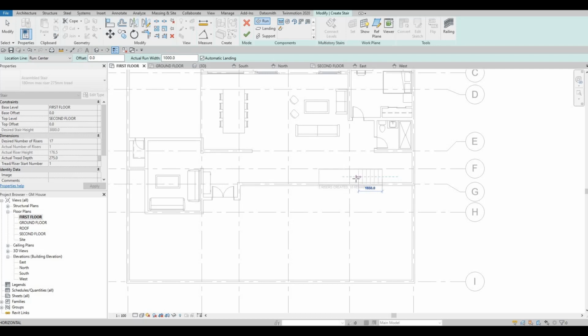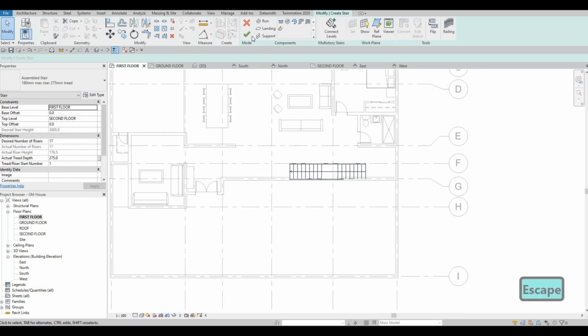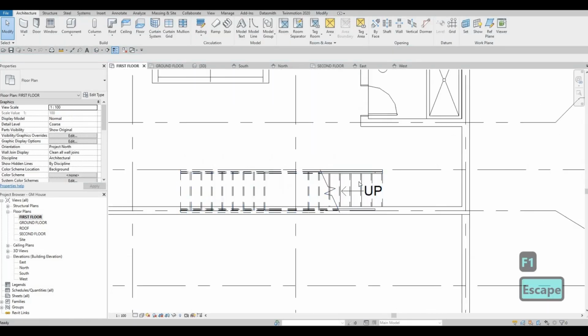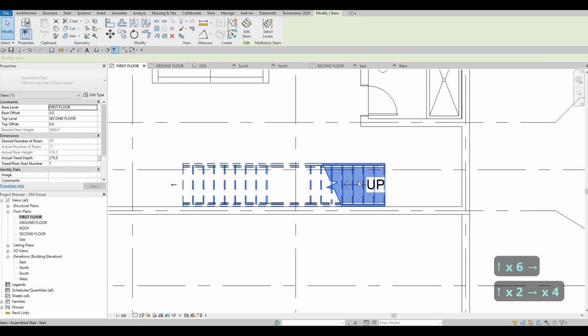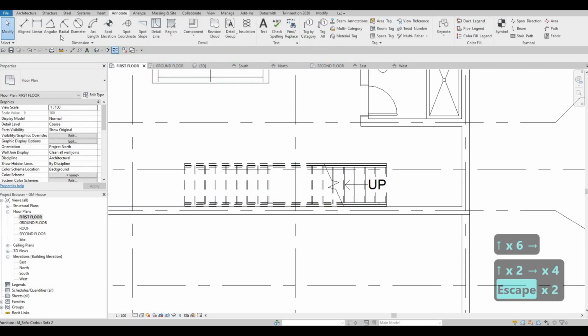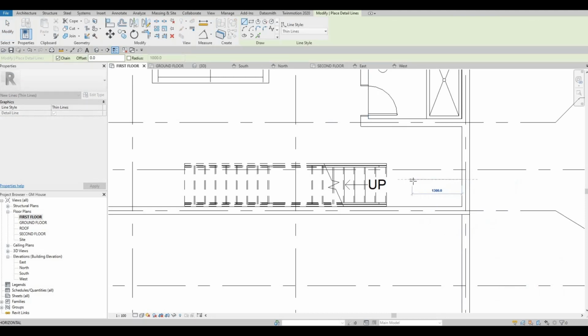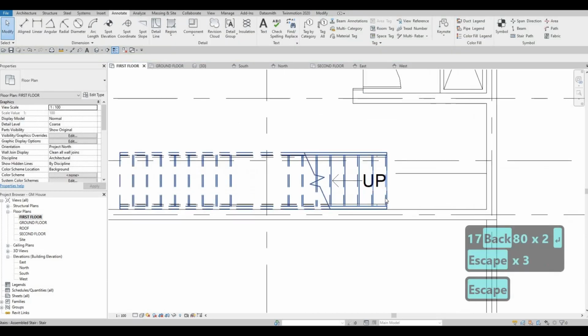Right now it's creating 9. I have 8 remaining. I want to have a landing and then the rest of it. So here I'm just gonna click finish. I want to move this, and then I want to create a detailed line so that I can be accurate. So around 1800, let's make it 1800, and then I'm going to align it there.